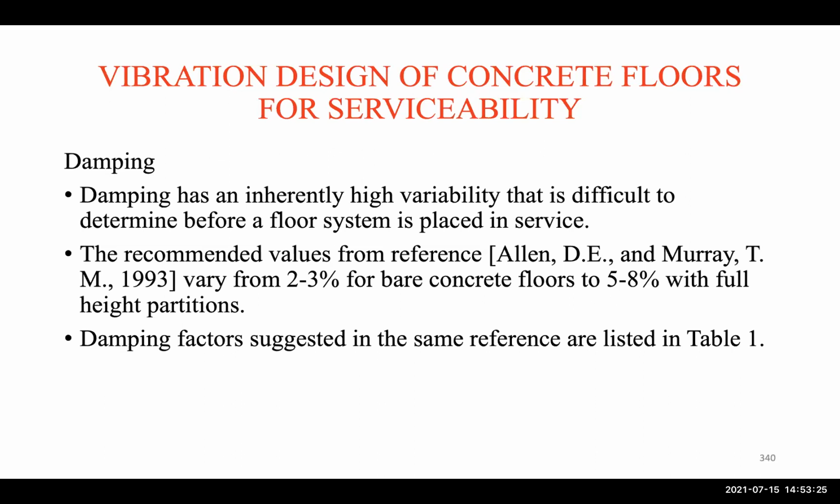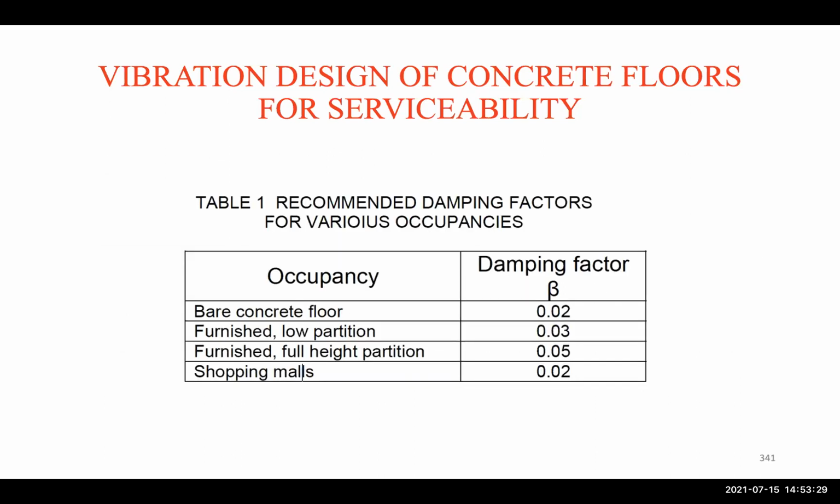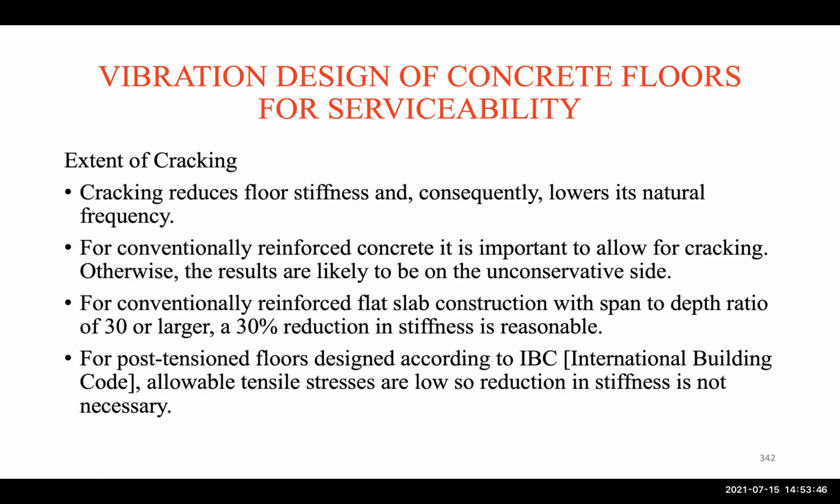Okay, so the damping factors suggested in the same reference are listed in Table 1 here. Okay, and by Allen and Murray, we have these damping factors for different types of floors: bare concrete floor, furnished low partitions, furnished high partitions, and shopping malls. Okay, so we can use those.